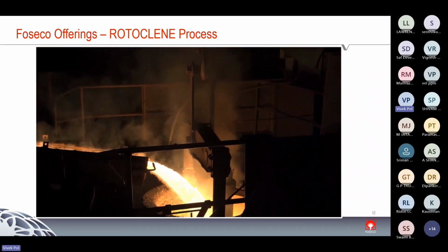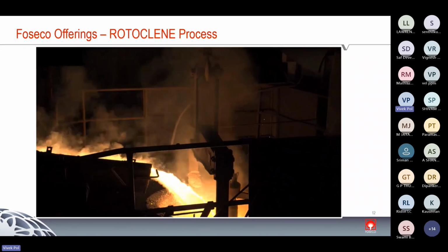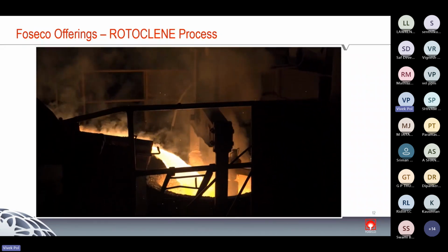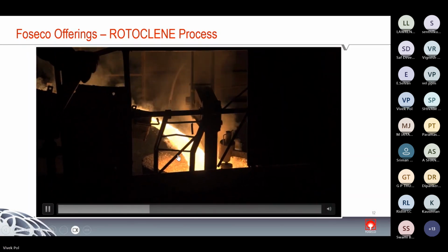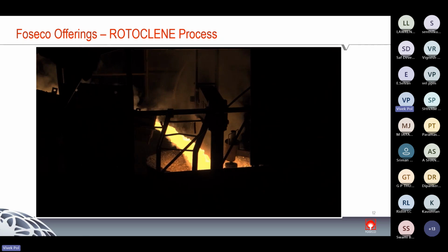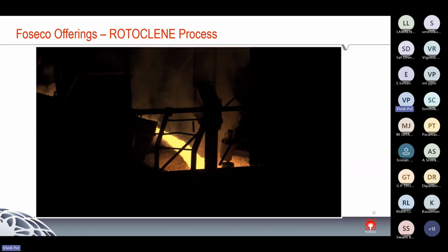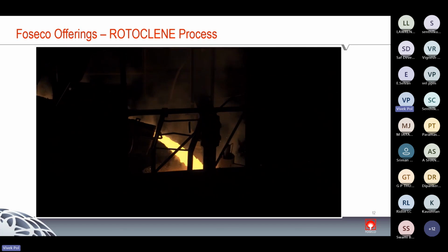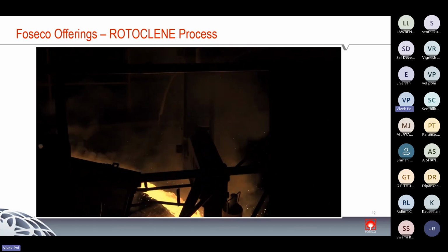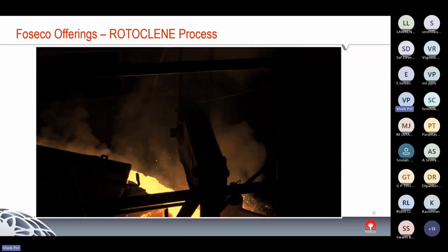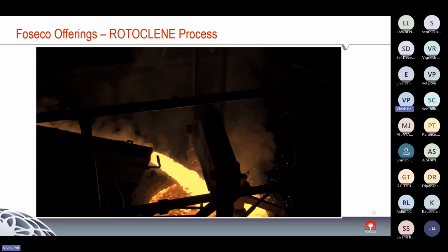You can see in the video, for a steel foundry, during tapping a lot of air is also introduced with the metal, and because of the air, inclusions and bimetallic films are developed in the metal. This operation we cannot avoid. We cannot tap the metal under vacuum or something like that to avoid air entrapment.